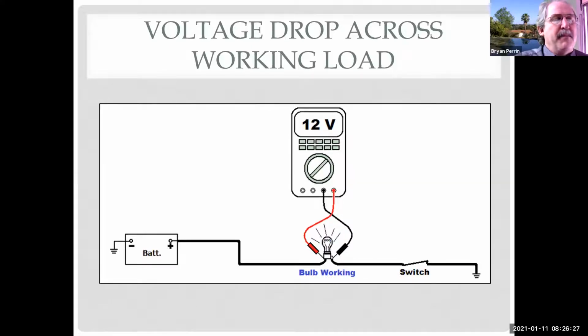The mistake a lot of people make is they unplug the light bulb and then check for 12 volts. Well, if you do that, we're checking for voltage potential, not actual voltage. So therefore, I might put a light bulb in and it still doesn't work. And you unplug it, you check, and you got 12 volts, but the light bulb doesn't work and you're really confused. That's why we always back probe things, because I have a complete circuit. Ohm's law says that if I have one load in the circuit, it should use all of the available voltage. And this proves that it does.